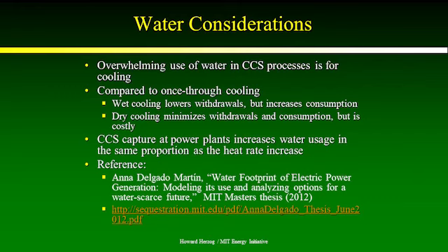One of the things we looked at in this thesis is we can see the amount of water needed by carbon capture when you add carbon capture to a power plant really correlates very well with the heat rate. So when you put carbon capture on a power plant, it reduces the plant efficiency because there's more parasitic loads, which then increases the heat rate, and that rate of heat rate increase will also be about the same rate as water increase for that plant.